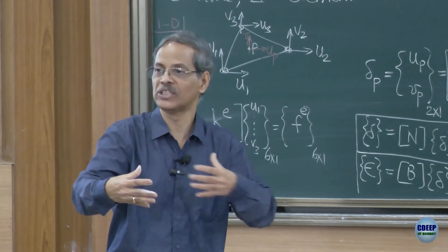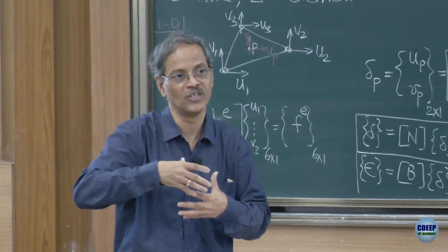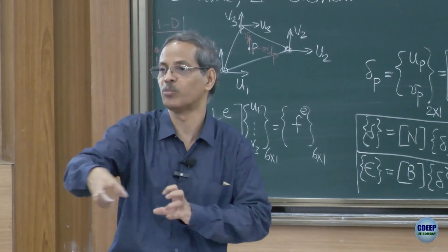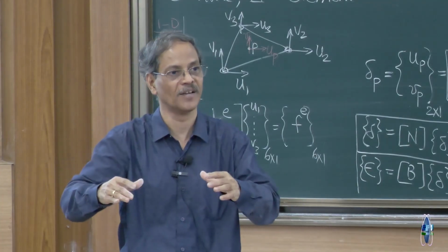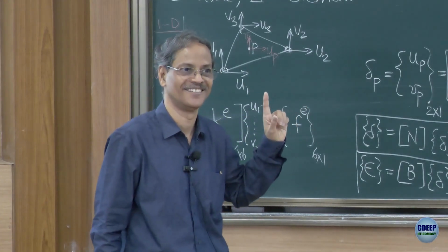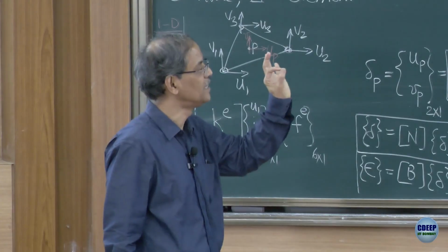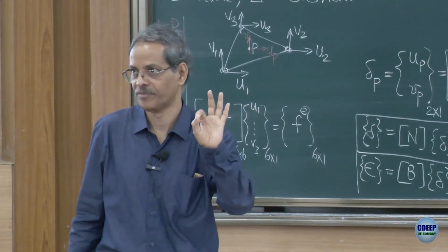As through the thickness of the material, such effects are less and less. So, you will control the composition of the material, functionally grading the material properties. So, then within the element D will change from point to point. So, B, D are likely to vary, if at all, within the element.